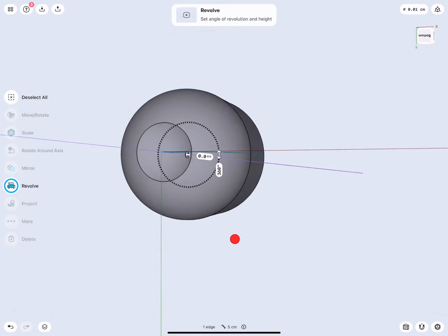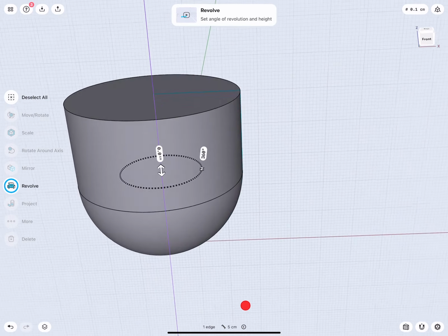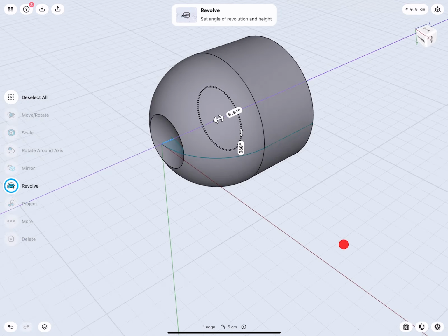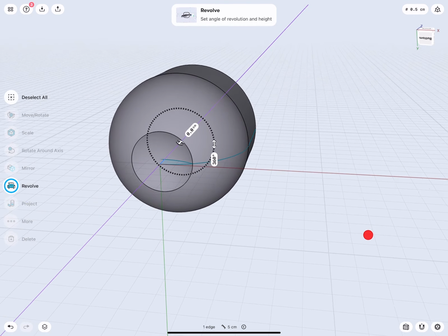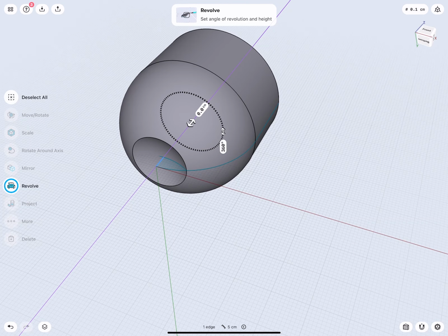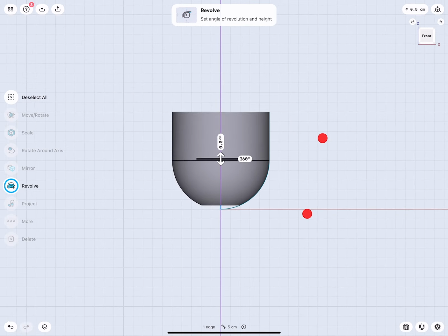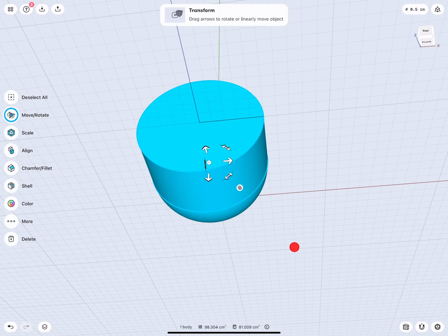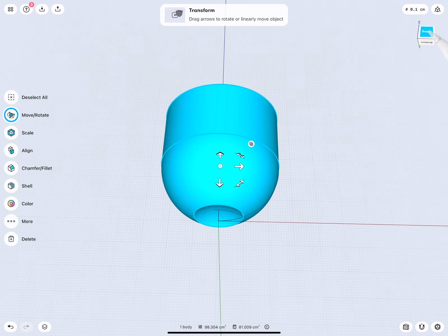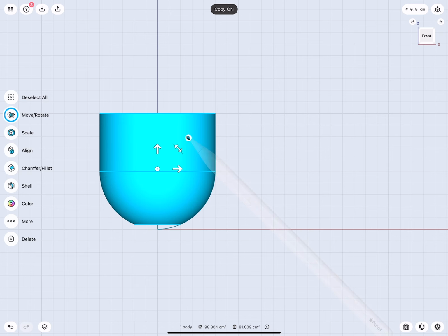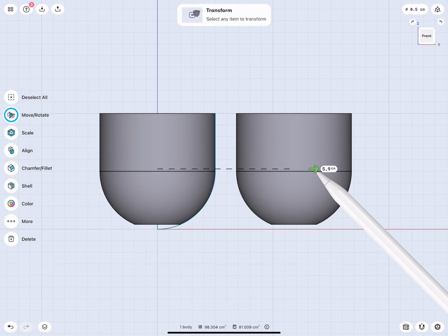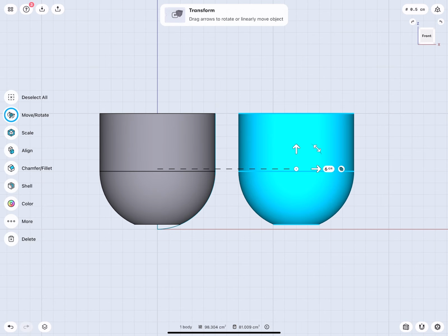Let's do a revolve, and there we are. So you see, we very simplistically created a sketch and then created the required geometry. And this building element will help us a lot to create everything we need. So what would be the next step? We know that we have 6 of those next to it. So I can do a little test, showing you a little bit of a design process now. We double tap the object, select it, move this over, and I would like to have 1 centimeter of distance. There, very good.